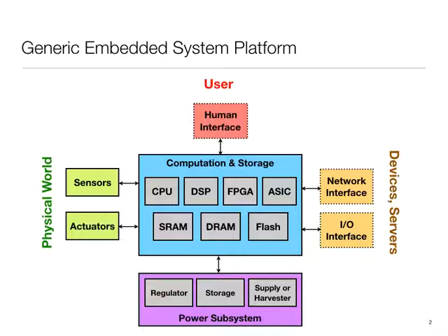Network interfaces, oftentimes it's radio, sometimes it could be Ethernet or some other wired interface, and then I/O interfaces are for talking with off-chip sensors and all. So this is where you have things like serial bus and I2C and SPI and USB and those kinds of things. And again, the boundary sometimes gets muddy because you can run network protocols over some of these I/O interfaces also. So at the end of the day, it's just sending bits over something.